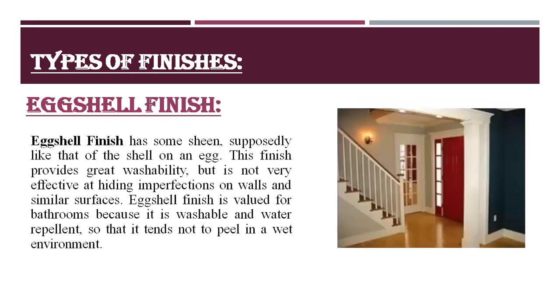Third is eggshell finish. Eggshell finish has some sheen, supposedly like that of the shell on an egg. This finish provides great washability but is not very effective at hiding imperfections on walls and similar surfaces. Eggshell finish is valued for bathrooms because it is washable and water repellent, so that it tends not to peel in a wet environment.